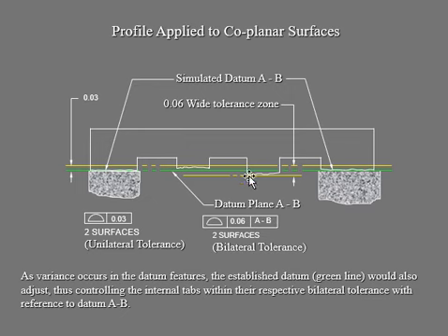So you have two different tolerancing for this section, that section, and then the middle section: two lines, one line unilateral, two lines bilateral, and then one line unilateral going a different profile right there. And that's what we call profiling. You are tracing the outline of that in this view. Don't forget the view.